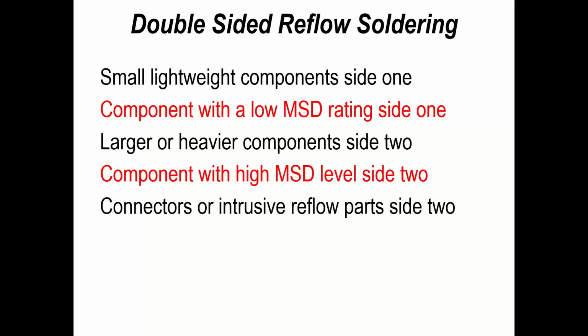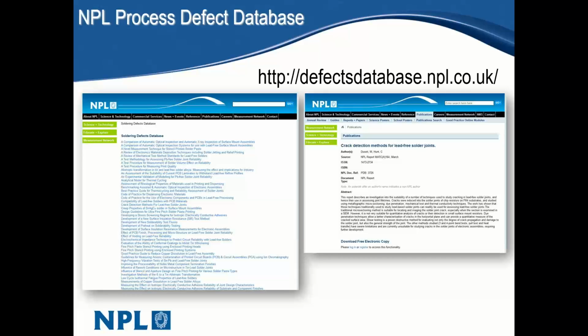So if you're running polyimide boards and you go through a water wash and then hold the boards for a period of time before you go into the next process, that might be a reason for baking the board. So just think about the next steps in the process, and control those just as well as you did the first parts of the process.